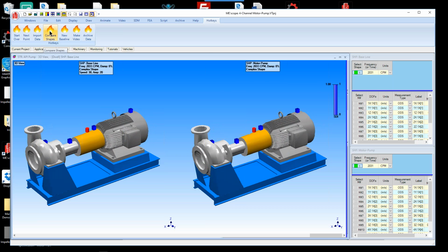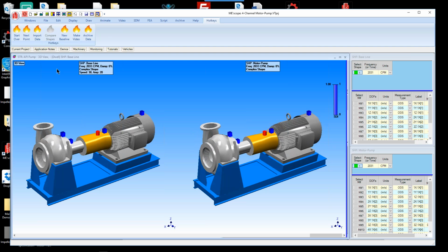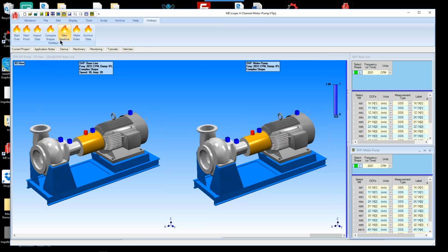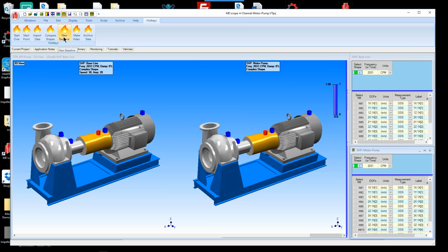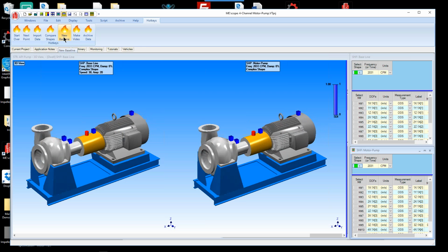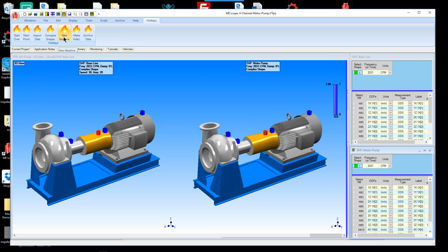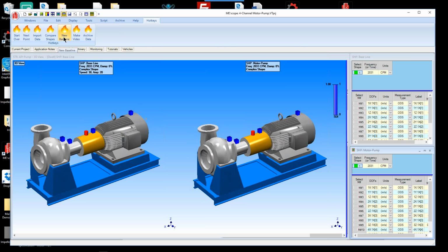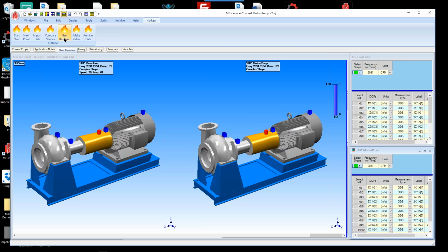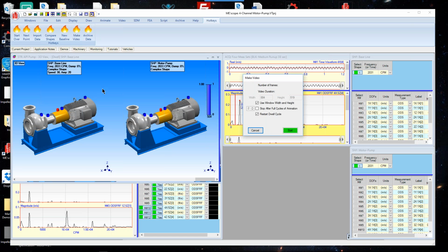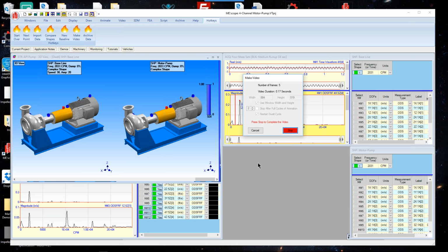So we're comparing these shapes right now. I press this hotkey and that will basically show me the same thing. And now I go to the next hotkey here. Well, the next one says new baseline. So we'll go back and use that one to set the left-hand shape data as our baseline and compare that with the right hand. And then we'll record some data that shows a difference between the two. I'm going to make a video here. This is one of the features in MEscope. Now what it's done is made the window a little smaller, and now I start the video recording.